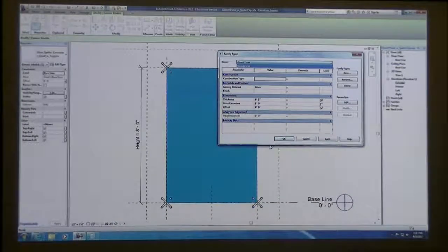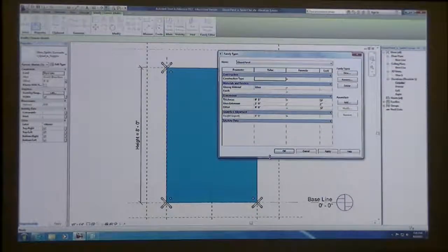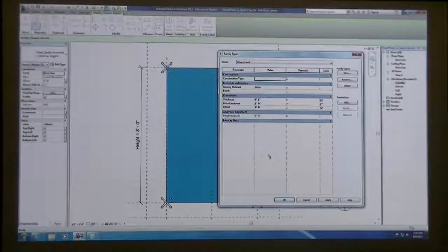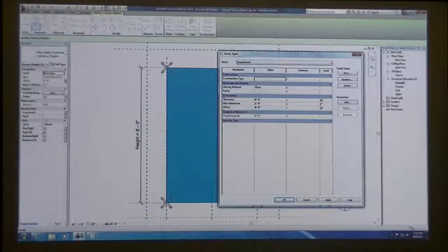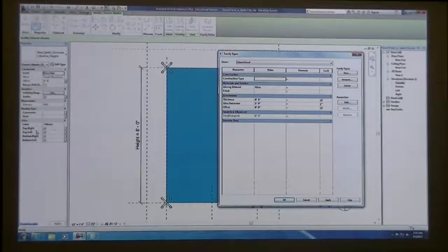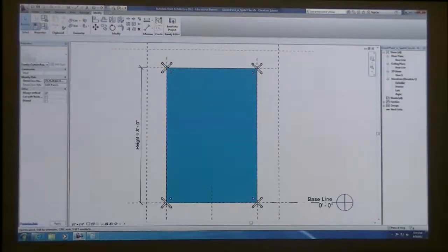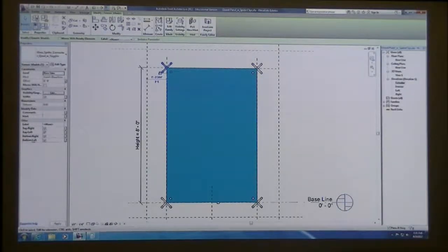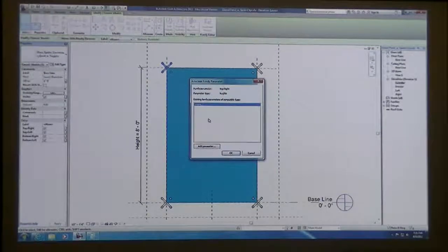And what you're going to have to do in order to make that happen is add a lot more yes/no parameters in here that reference these parameters. So you can see it'll get kind of embedded and pretty deep. But if you do set it up, instead of toggling these on and off over here, you're setting this button to equal a yes/no parameter that's now in this family environment. And then you could toggle your different, yeah.